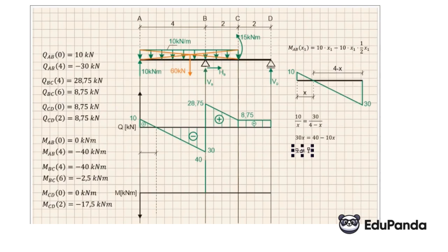And this value of x, looking from the left side, that is from the beginning of the beam, if we denote the continuous load value as q, and the value I denote as TP, the initial shear force. This is the first force from the shear force graph in the area that interests us, which for us is 110 kN.